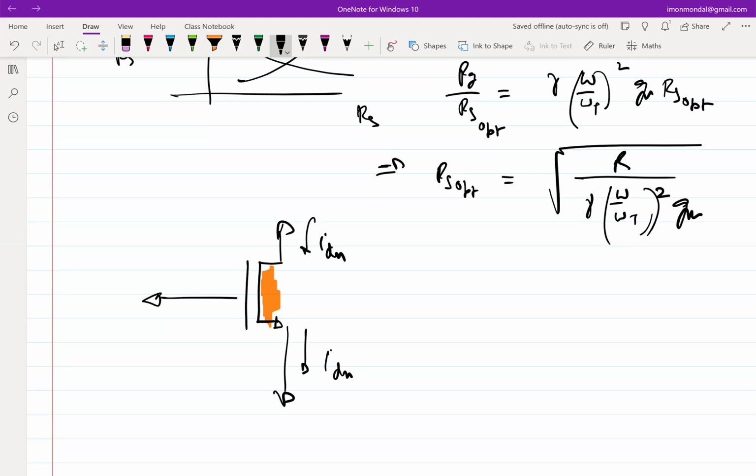But you should understand that this is a capacitor, which means that there is the root, and this channel has a resistance, a distributed resistance, and you have a capacitance throughout. If there are fluctuations in these resistances, or noise voltage getting developed in the channel due to these fluctuations, then there will be some effect through this capacitor. So part of the current comes out through the capacitor as well.